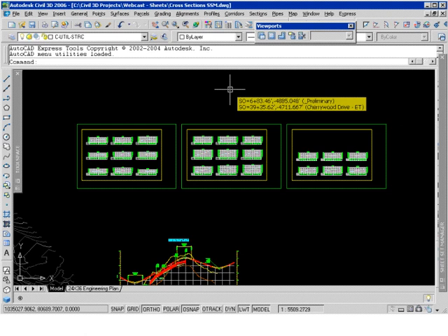Well, why I really wanted to point that out is that this is powerful, and the way that we've set up this style here with this green and yellow frame, that is going to correlate to what we might want to have on our title block, the yellow frame being where we're actually going to plot the cross sections, the green frame being maybe the outer extents of our title block. Again, all set up in that style. So what I'll do is take advantage of those frames being there for the use in Sheet Set Manager.